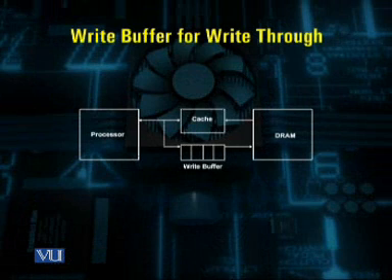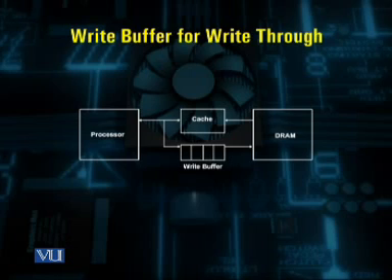Furthermore, if the stores are too close together or the CPU is so much faster than the DRAM cycle time, then you can end up with an overflow of the write buffer and the CPU must stop and wait.